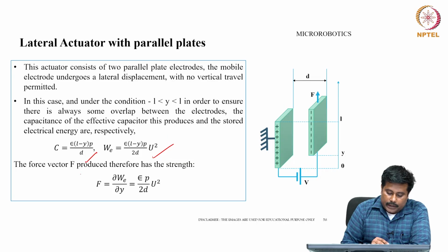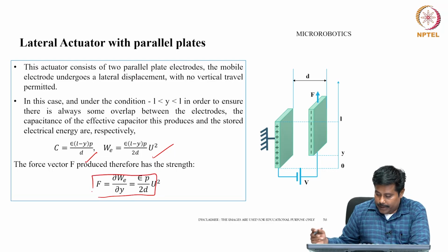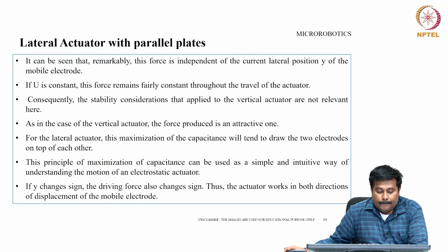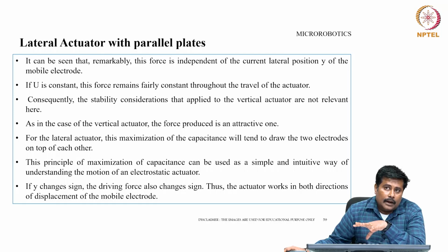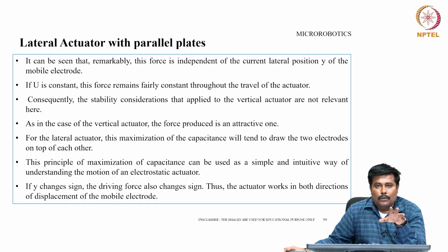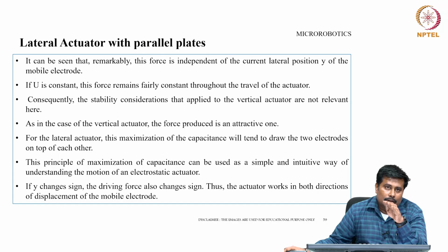So, the force vector F produced has a strength which is represented by this equation. Now, it can be seen that remarkably this force is independent of the current lateral position y of the mobile electrode. That is, if u is constant, this force remains fairly constant throughout the travel of the actuator. Consequently, the stability considerations that apply to the vertical actuator are not relevant here.